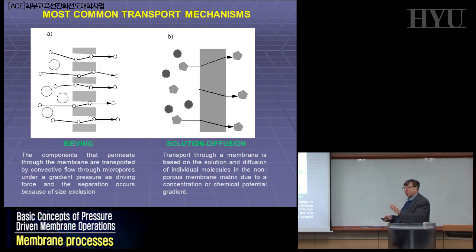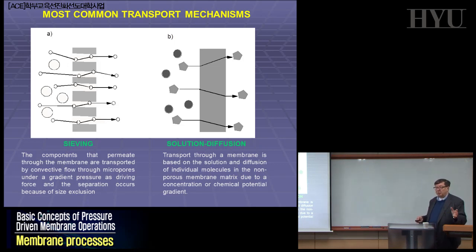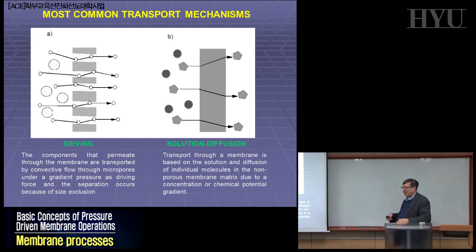At each temperature there will be a different value of this solubility, and another phenomenon, which is a kinetic phenomenon, diffusion. The product of the diffusion coefficient and the solubility coefficient is what we call permeability. When you have this kind of mechanism, permeability is nothing more than the product of solubility and diffusivity. Okay? Both cases are simple, extreme cases, and real life is always in between. So there is a situation in which these two cases can overlap.